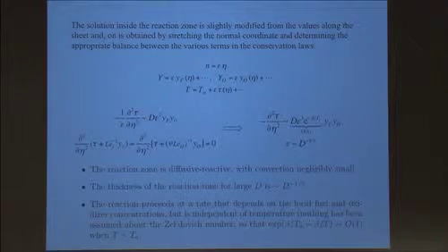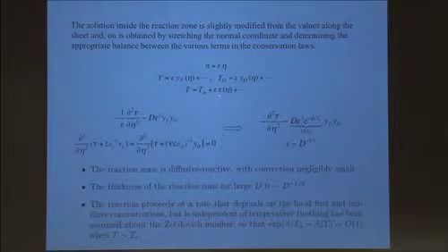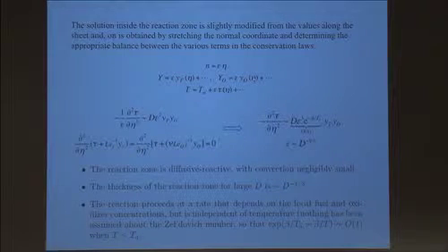And the temperature is near the adiabatic temperature of complete combustion, so it's perturbed as adiabatic temperature plus a perturbation. So tau represents the temperature, and little yf, little yo represent the fuel and oxidizer.